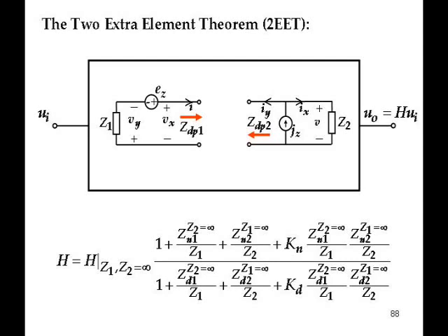The only difference is there's an extra subscript n in the numerator parameters. And that means that those quantities are calculated under conditions of the output null, whereas the denominator ones are calculated under conditions that the input ui is 0. So there are two different sets of conditions, but the format is symmetrical.